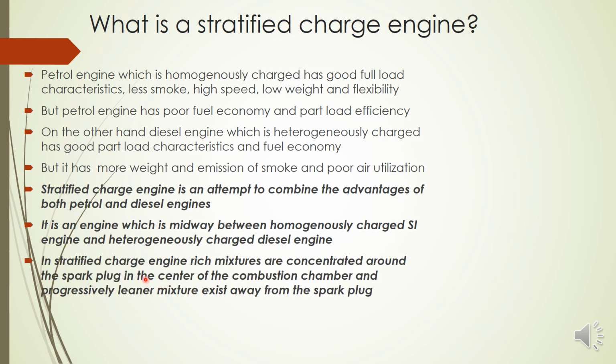In a stratified charge engine, the rich mixture is concentrated around the spark plug. We know that in a petrol engine, ignition takes place by a spark plug. In a stratified charge engine, we are providing a rich mixture near the spark plug, and away from the spark plug in the combustion chamber, we will have a progressively lean mixture. So that is the idea of the stratified charge engine. It is a petrol engine.